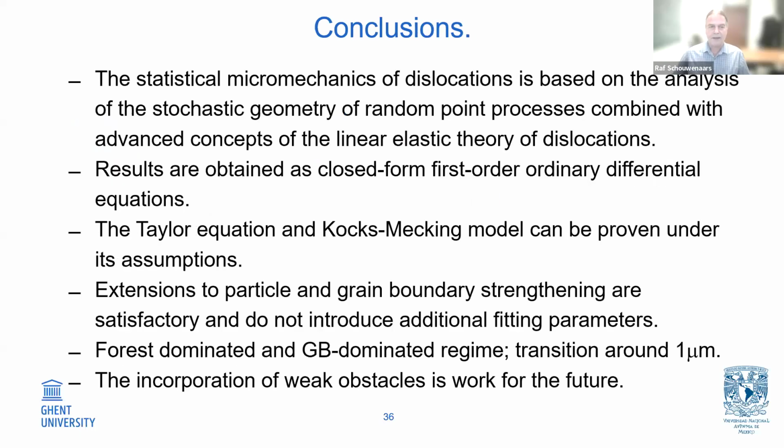So, conclusions. What we propose is statistical micromechanics of dislocations, based on the analysis of the stochastic geometry of random point processes combined with advanced concepts of the linear elastic theory of dislocations. All results are obtained as closed form, first order ordinary differential equations. We can mathematically demonstrate that the Taylor equation and the Kocks-Mecking model are valid. And in the same analytical way, we can extend these models to particle and grain boundary strengthening in a quite satisfactory way without introducing additional fitting parameters.